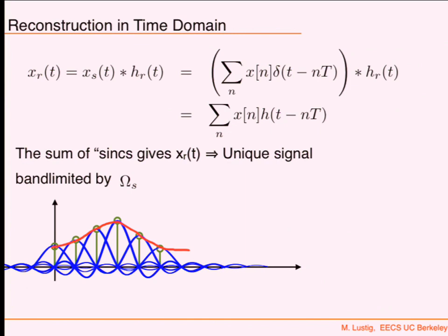Absolutely. But only within the bandwidth that they have, not outside. So you'd see dropouts in the signal, but that's fine. You don't get new frequencies. Hence, if I construct a signal by shifting and scaling sincs, it's going to have the bandwidth of that sinc. That's it. Not anything else.